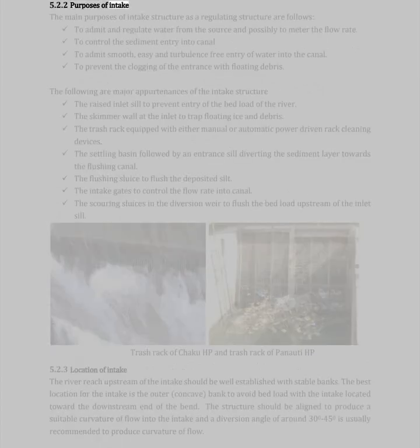5.2.2 Purposes of intake. The main purposes of intake structure as a regulating structure are as follows: to admit and regulate water from the source and possibly to meter the flow rate; to control the sediment entry into canal; to admit smooth, easy, and turbulence-free entry of water into the canal; to prevent the clogging of the entrance with floating debris.